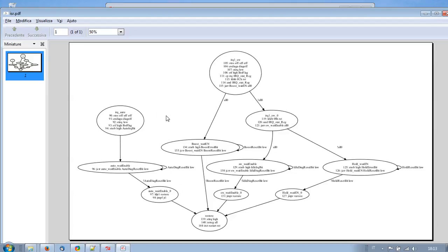And the danger is that the code executed in the entry point, which is basically some initialization code for the interrupt handling, can be missing in one interrupt service routine or the other. The solution would be to have a single entry point and then at runtime decide which interrupt has occurred.